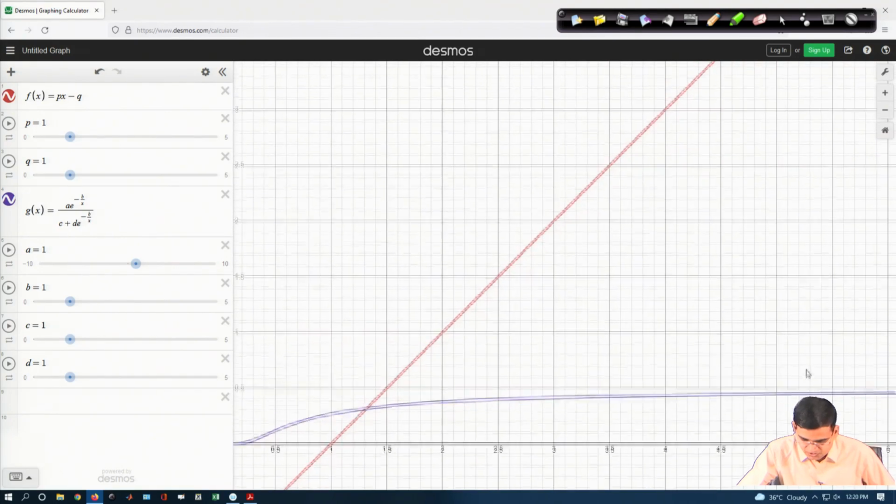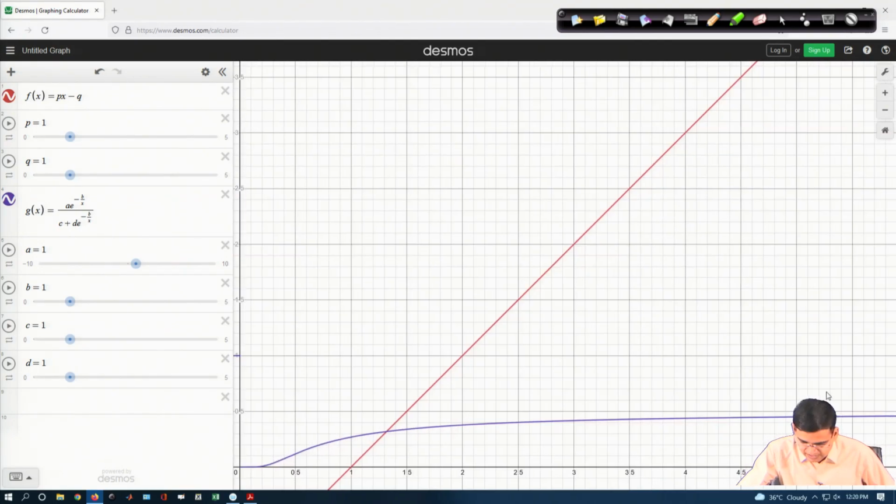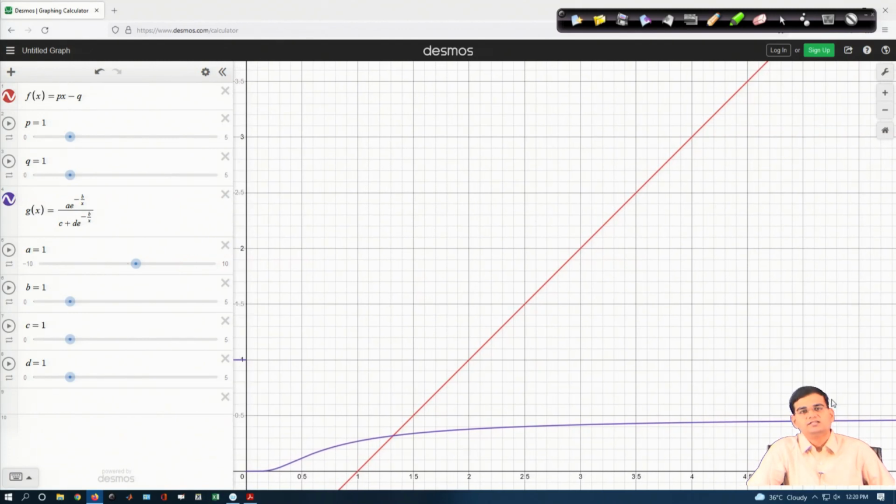Okay. So, now what I see is that I have the left hand side involving exponential. So, you have this nonlinear curve, I have the right hand side which is a straight line, you get this, and then you get one point of intersection, and therefore, this is your T steady state. So, you fix the flow rate, you fix the feed concentration, you fix the jacket flow rate, you fix the jacket temperature, you get one steady state. Looks very simple, very trivial in fact, right.